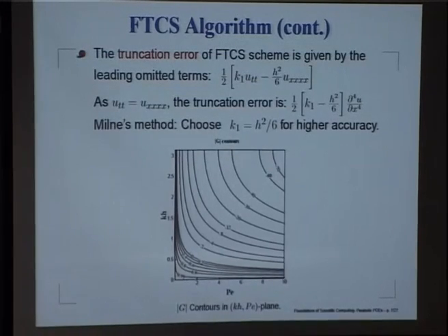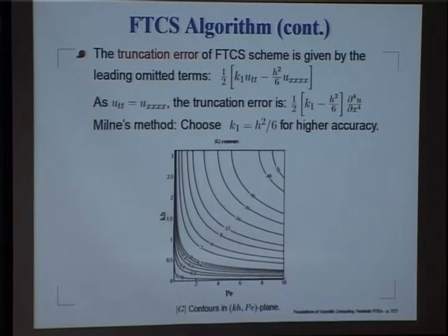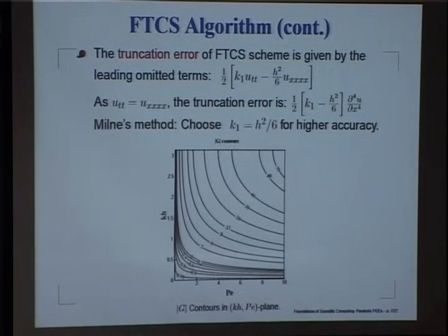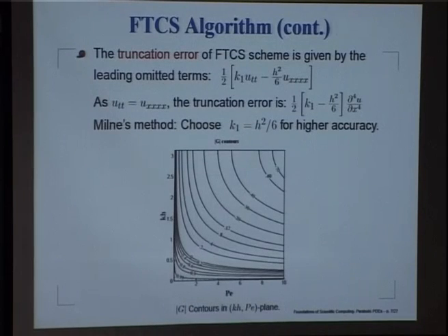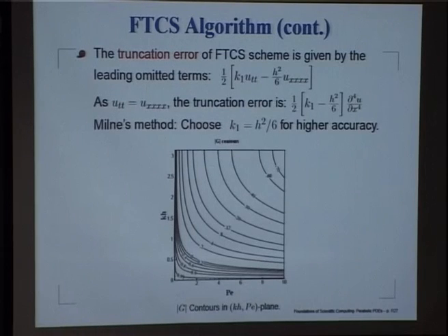So, you can see the dramatic transformation, because this method was unstable in this part of the domain. Even if I am talking about a Peclet number of 0.01, I would be looking at here. So, it is quite okay. It will remain stable, no problem there. However, look at the value of G. This will take all the way from 1 to virtually, let us say, 0.2, 0.15, that kind of value.